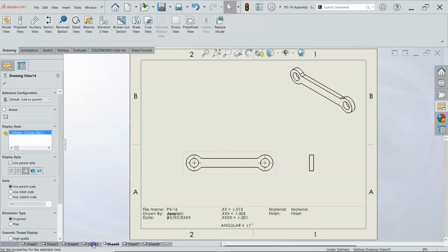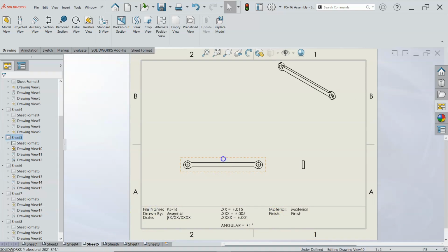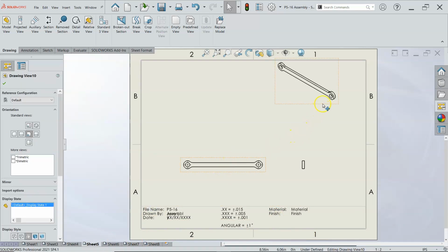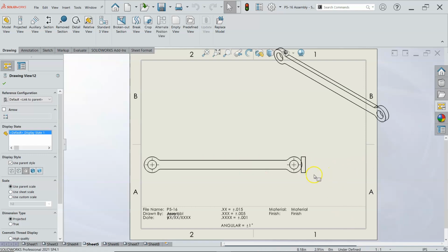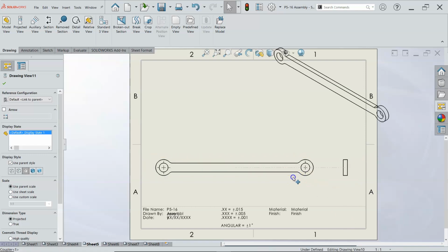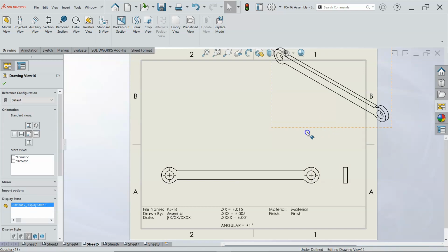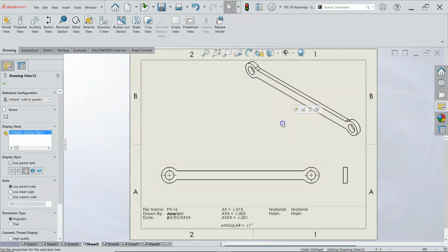And we'll go back to the coupler. Because of the size, it might have been better to have the top view, but we'll see what it looks like at 1:1. All right, and since the ISO is taking up a little bit, I can also go from the sheet size over to the property manager for just that view, use a custom scale, and it can remain at 1/2.